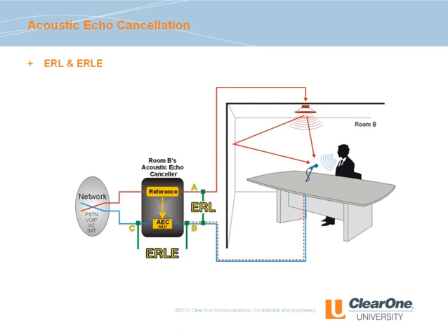This involves many factors, but most importantly, the talker audio at the microphone should be higher in level than the acoustic echo picked up by the microphone. Improving ERL is a major contributor to improving talker to echo ratios at the mic, ensuring an intelligible, full duplex audio conference. ERLE, or Echo Return Loss Enhancement, is the loss in level of the acoustic echo that the echo canceller adds, the difference between point B and C.